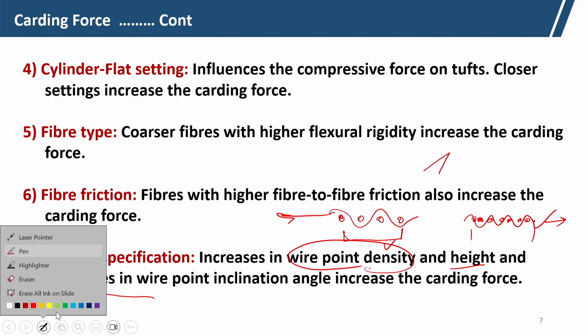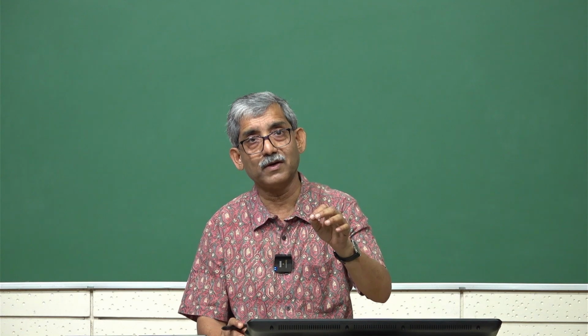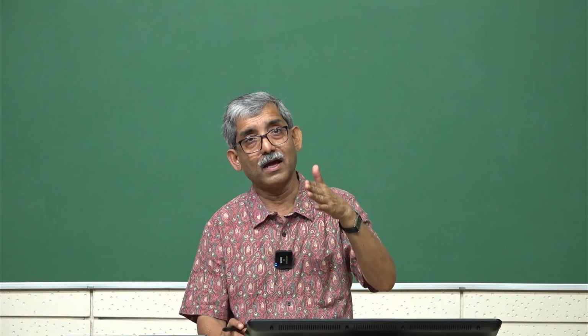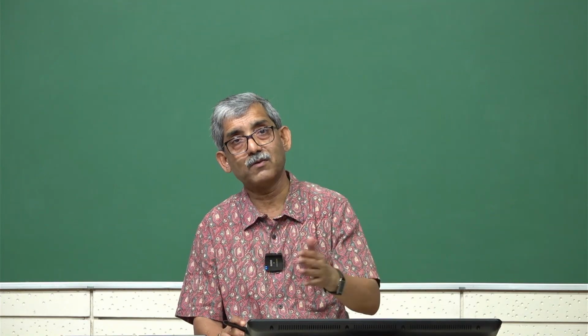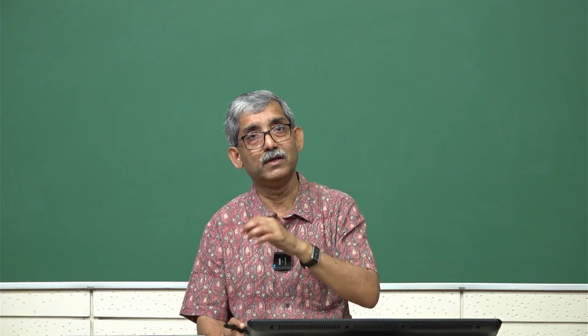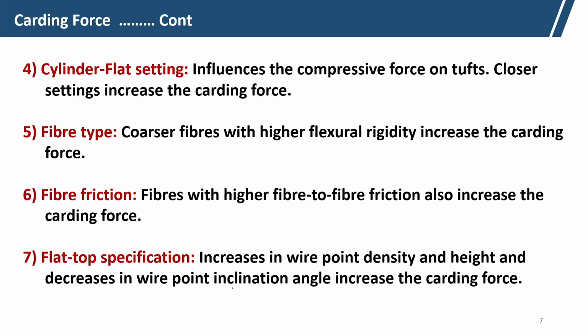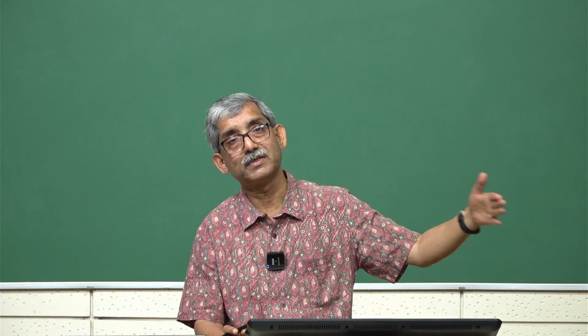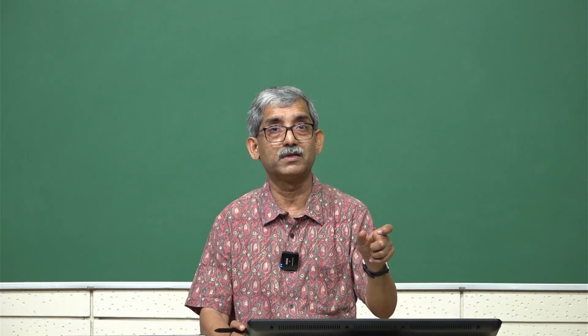Where we do not need higher carding force, like in case of synthetic fiber like polyester, the degree of inclination is high, and in case of cotton and other fiber where we need to open up, we need higher carding force to open up fibers. So, we need the lower inclination, that we have seen by earlier derivations. For cotton, for wool we have seen, for cotton it is less than 74 degree.